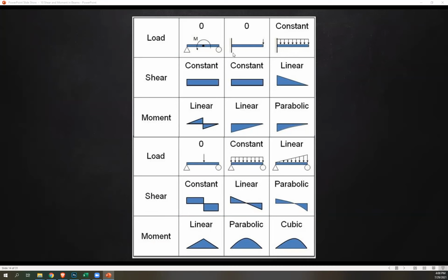So going down, or if we start here, going up to the right, going down, again, that's a rectangle. Now we have a uniformly distributed load. There's a reaction here again, so we're going to go upward. And then our line is going to go 1 degree higher. This is a straight line, so 1 degree higher is a slanted line. That's why this is an incline.